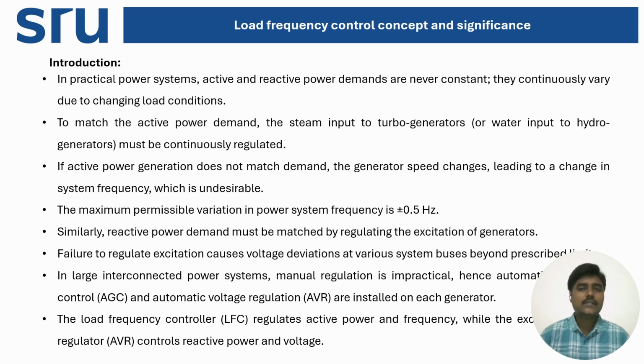In today's lecture, we will cover load frequency control, and the primary and secondary frequency control loops. First, coming to the load frequency control concept. In a practical power system, active and reactive power demands will never be constant because our load keeps on changing continuously.